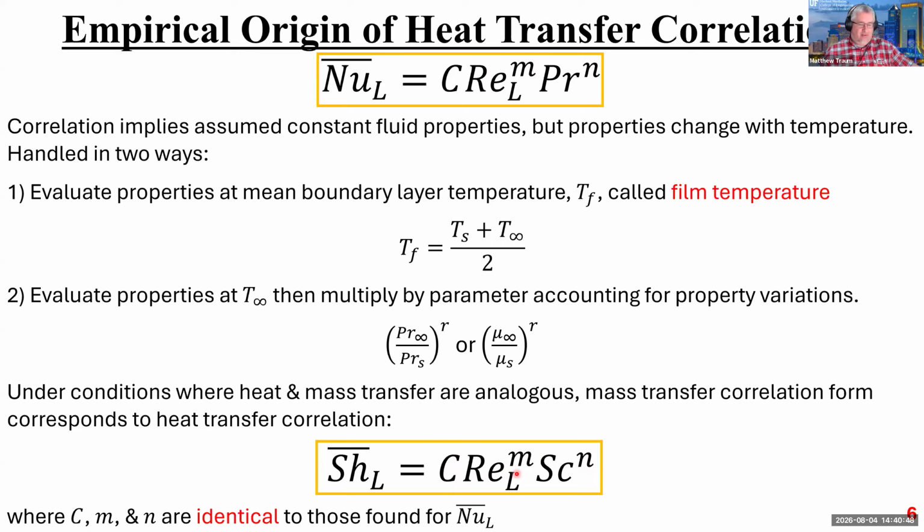And this is actually a very powerful realization that's used a lot in experimental heat transfer, because it is often easier to measure mass transfer just by weighing something and seeing how much mass is diffused away from it than it is to measure heat transfer or temperatures of weird shaped objects. And so experimenters will actually build strange geometries that they're interested in finding the heat transfer for out of solids that sublime. So naphthalene is one of those solids.